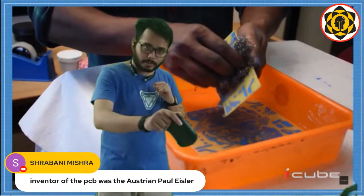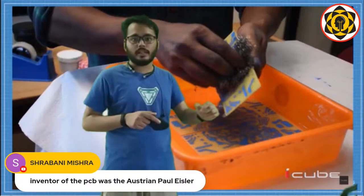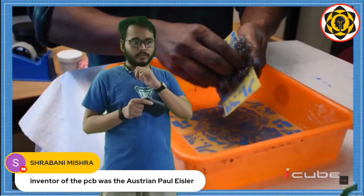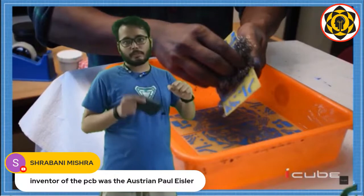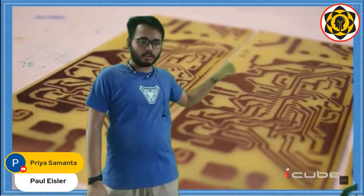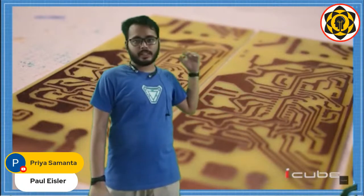So we are going to rub it with a steel wool or a file or a sandpaper, anything like that will just rub off the paint from the surface. So after rubbing off the paint, this is the result. As you guys can see, the copper places are there where we want. The other places have been etched away by the ferric chloride.